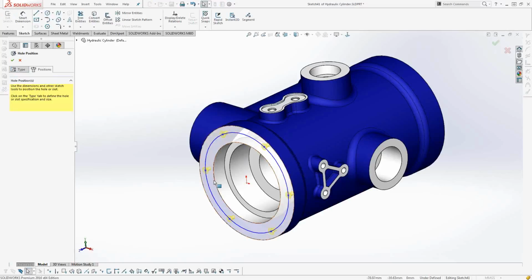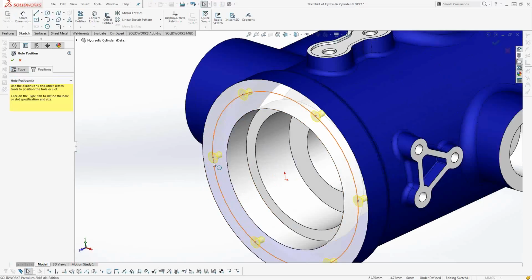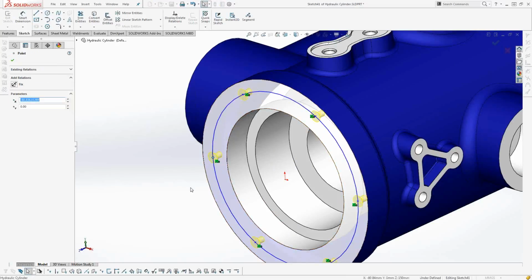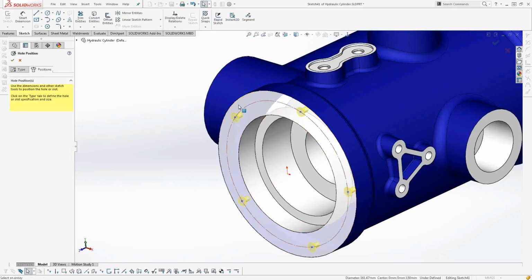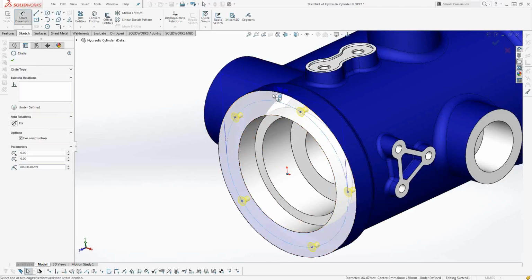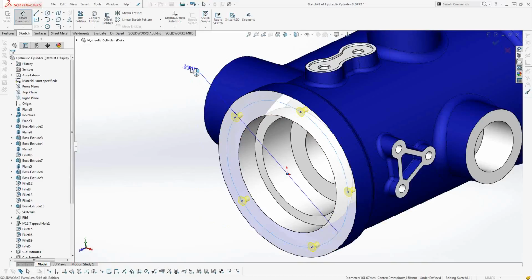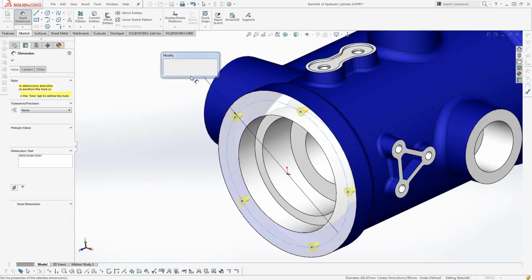Now, what is new in SolidWorks 2016 is that in the past, these points would be placed, and then basically there wouldn't be any relationships between them. So if I did something like delete this sketch point, notice that it now evenly redistributes those points across that arc. Pretty cool, all right? So if I need to come back in here, maybe apply a couple more dimensions, let me do that pre-select dimension option that I just showed you guys.